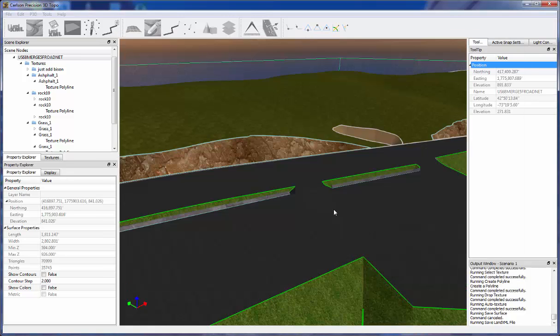And in the LandXML 2.0 file format, of course, we're saving not only all of your surface modifications as a LandXML surface, but we're also saving all of the boundaries and all the textures within this LandXML 2.0 file as well. And again, any other software that supports LandXML 2.0, all the texture images and everything that you see here is embedded within that LandXML file itself.